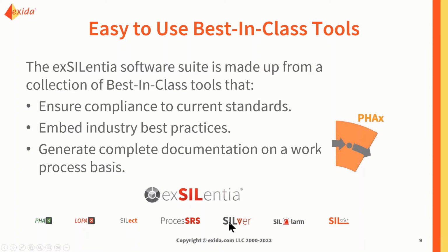The Markov model concept is very complicated. But when we talk about the mathematical methods, basically it's an expansion of different kinds of matrices. As I would quote our CTO, Iwan, you can actually do it in your Excel sheet, but it can be very cumbersome if you have a lot of different votings, like 2 out of 3 or 4 out of 3, stuff like that. So that's why we provide this particular module for people to do the most accurate calculations for their SIL verification.